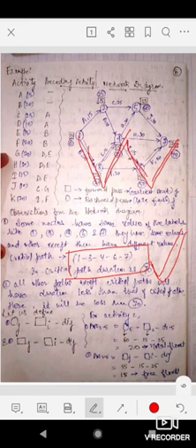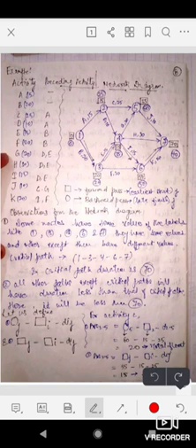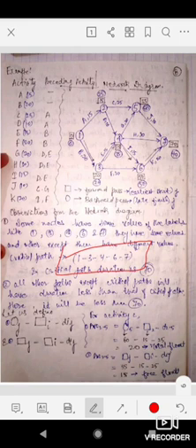If you delay, for example, activity B by 1 day, if you complete it not in 20 days but in 21 days, your project will be delayed by 1 day, because this activity lies on the critical path. So you can see from the precedence diagram, 1, 3, 4, 6, 7, this path takes 70 days for completion. So 70 days is the duration of the completion of the project.